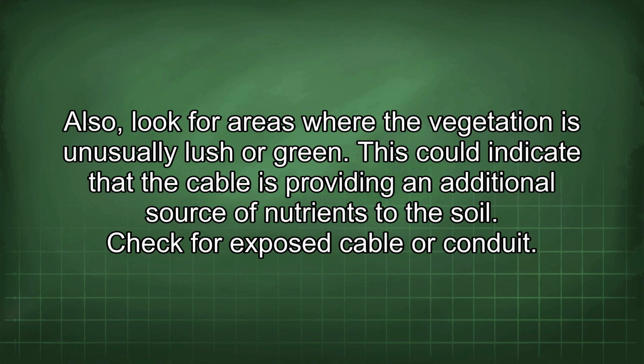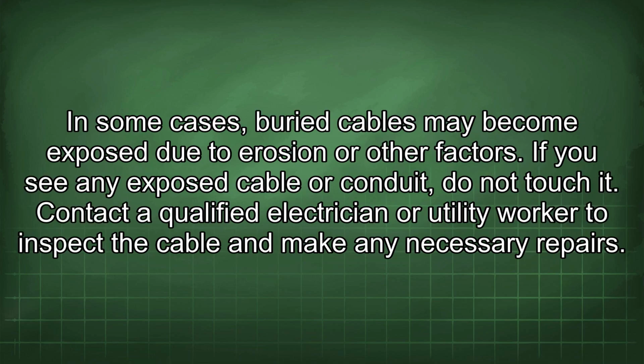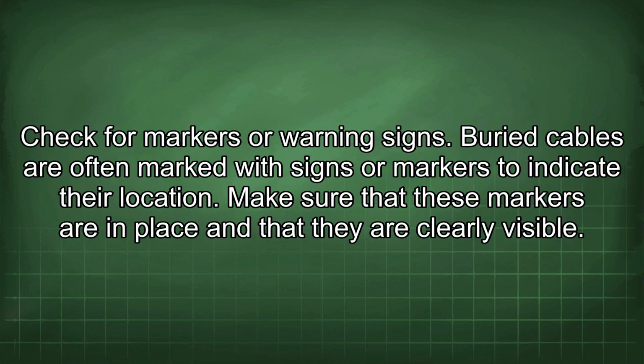Check for exposed cable or conduit. In some cases, buried cables may become exposed due to erosion or other factors. If you see any exposed cable or conduit, do not touch it. Contact a qualified electrician or utility worker to inspect the cable and make any necessary repairs. Check for markers or warning signs. Buried cables are often marked with signs or markers to indicate their location. Make sure that these markers are in place and that they are clearly visible.